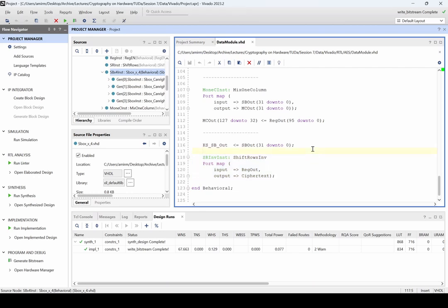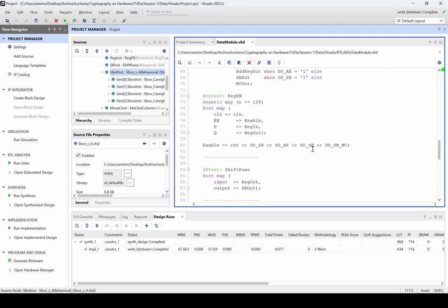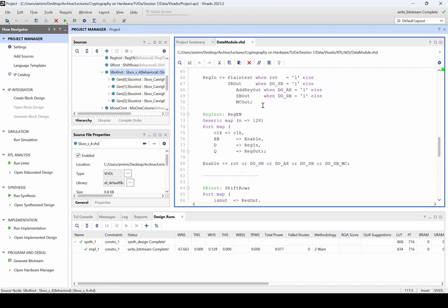Now we talked about this, and this is, as I said, the large multiplexer, but what you should consider is that we apply this column-based implementation to reduce the area. If the multiplexers are not done in a good way, very large multiplexers will be instantiated inside the hardware, and finally the implementation will not be as small as expected.